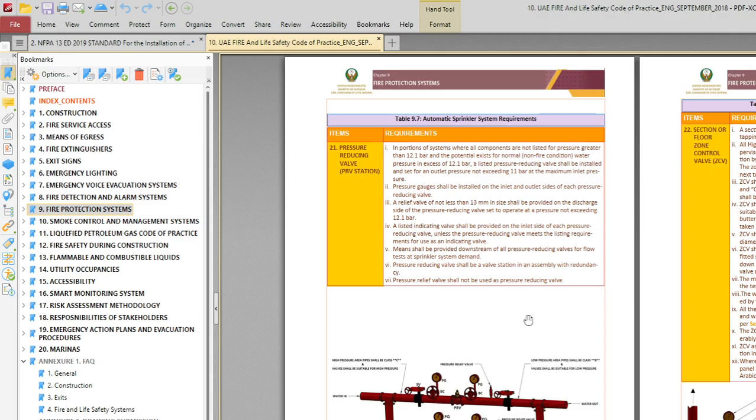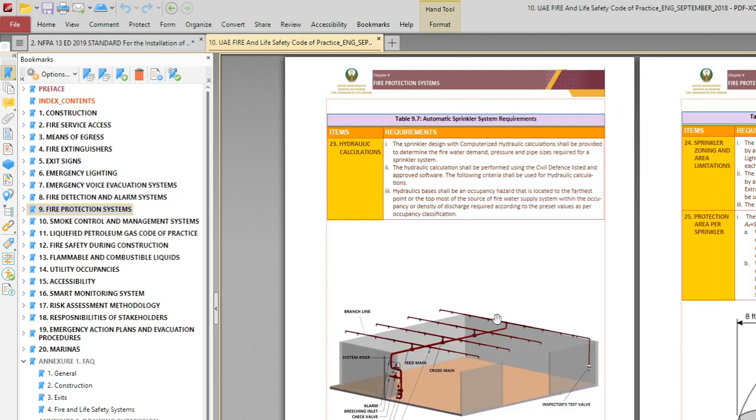In the system, what are the three systems we have? One is the sprinkler, another is the fire hose cabinet, and another is the fire hydrant, right? Standpipe. Yes. So that means we have to calculate internal or external, whichever is higher: sprinkler plus fire hose cabinet, or the fire hydrant. Now assume we calculated for the sprinkler. How do we calculate? 1,500 multiplied by the density for the different hazards, and then you calculate the total flow rate.